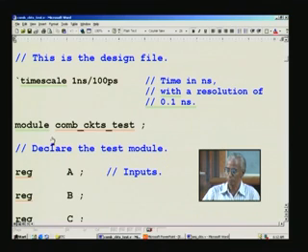But in this case, when you test and have a test bench, the test bench becomes even higher level than the design module, because the design is being called by this test bench. That is why we do not have IOs and have not listed them. Do not forget the semicolon, which tells that the module definition has ended, not that the module has ended. To communicate that the module has ended, you need an endmodule, which will appear at the very end of this code.